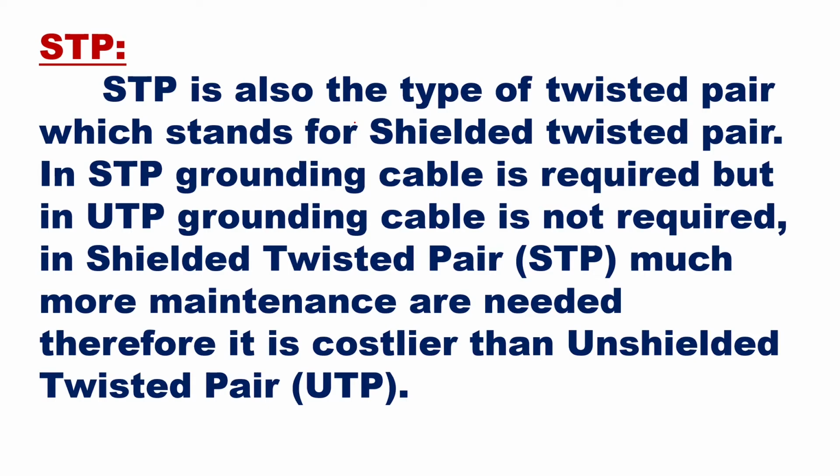And the earlier point, the grounding cable in STP is required because that extra mesh you put around the pair of wires can pick up noise. If you want to sort out that problem, then it should be grounded properly. That is why you require a grounding cable in STP.